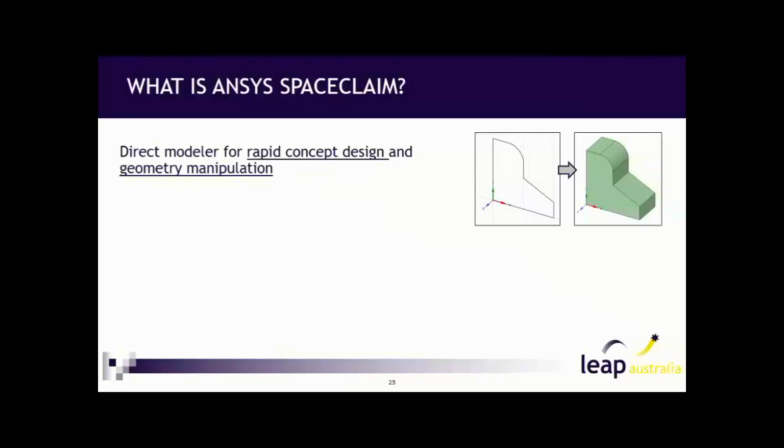There might be surfaces, they're all solids where you want mid-surfaces to do some sheet metal work, or they might have contacts that aren't quite lining up, or things that might be okay with manufacturing. We have small gaps that aren't really going to work with CAE. So we've got tools in here to fix all those small issues that will cause you errors.